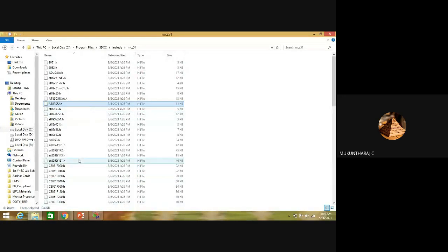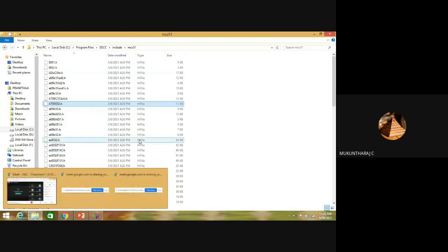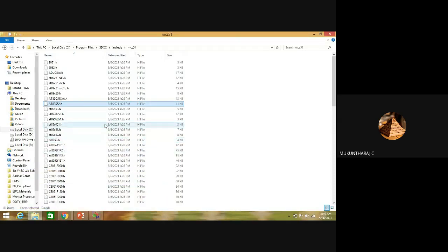So for our purpose, after installing SDCC, you can find a file called AT89S8252.h. That should be renamed as AT89S52.h, as we used in our program. You have to replace the older file name with the new one.